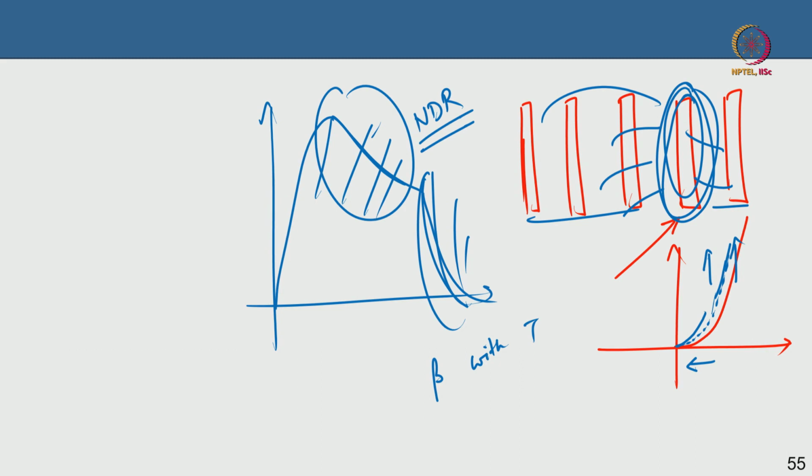At one point suddenly one finger will have this dramatic increase, the positive feedback of increase in current and lowering of the turn on voltage, and that leads to this collapse. And we talked about how the emitter ballast, an extra resistance that you put in the emitter, will try to mitigate this effect. It is called ballast, and then you can bias this device out of this collapse by coming again to this part, and then it will be fine.